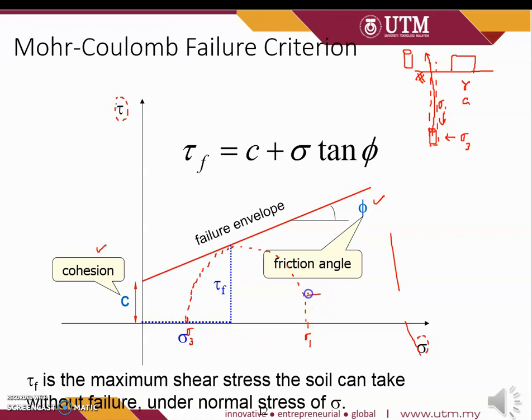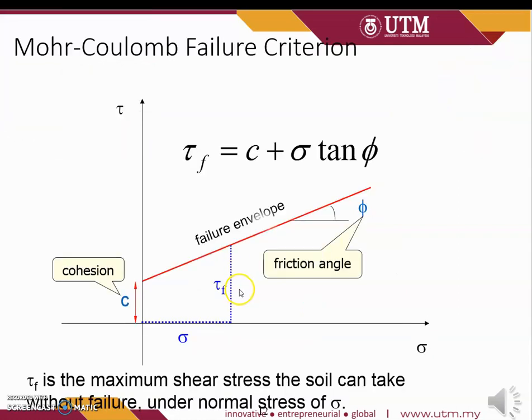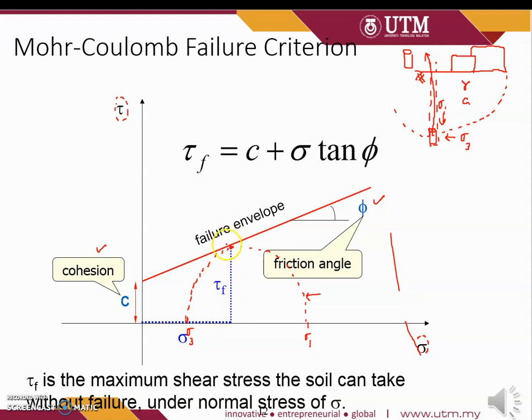So this curve is a Mohr-Coulomb curve. And this is the failure line. So the failure line might be, let's say, from having a bigger building. So the failure line might be here, and might occur like a circular failure line. The sample taken at the failure zone will touch the failure envelope. So at the failure envelope, we can read the shear strength at failure and also the normal stress at failure.